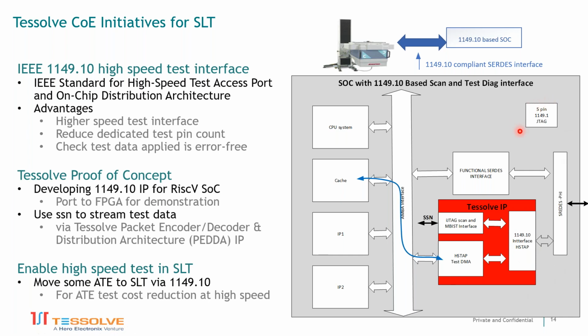If you push them across the JTAG interface, it's a very slow interface. So what we're trying to do, with 1149.10, is stick it behind the high-speed SerDes. On the chip we're working on at the moment, this is behind the USB interface, so you've normally got the USB going here, but in test mode you can push them into this IP here.